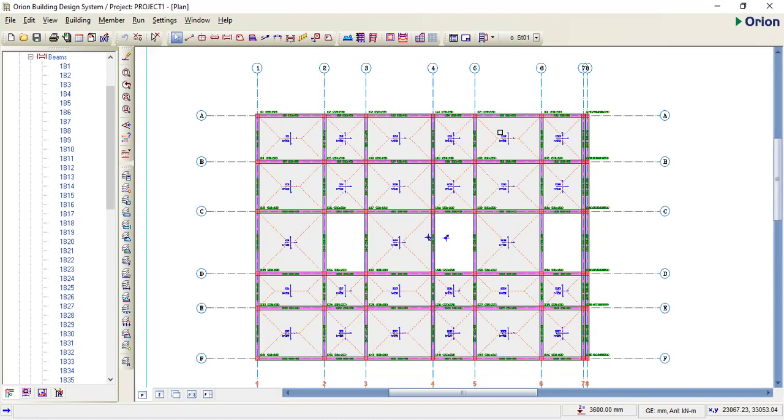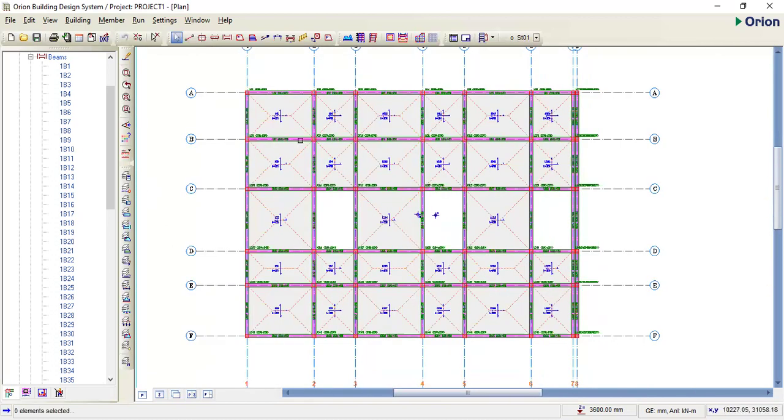Because in structural design, what we were told and what is in practice is that you start your design from the roof level, come to the second floor, come to the first floor, come to the ground floor, then the foundation is the last place you design. Because the load is being transferred from the roof all the way to the foundation. So you cannot design the foundation before you get to the roof. You come from the roof and the load transfers to the foundation, then you can now go to foundation design. That is why you can see for now, it's as if the foundation is silent. Okay? All right, so we are here now.